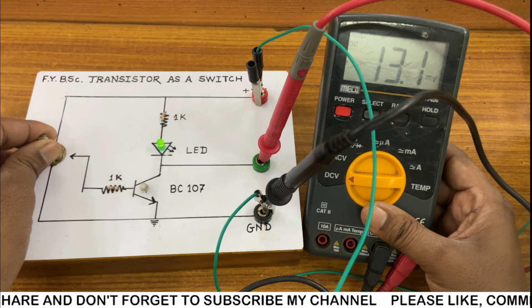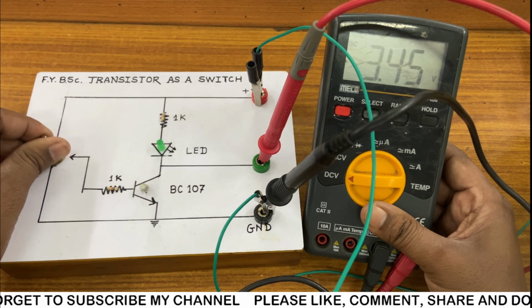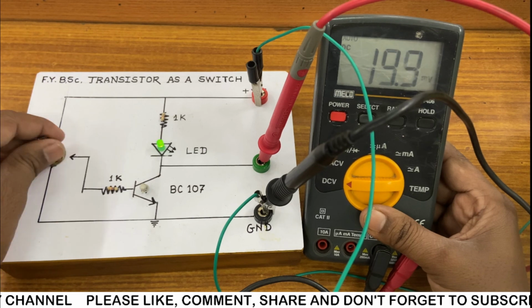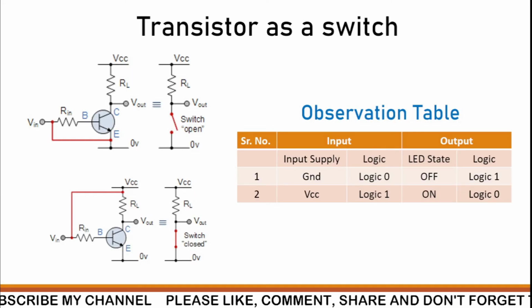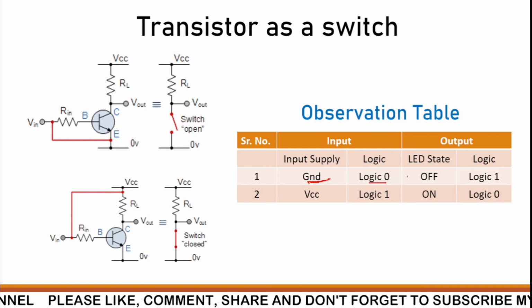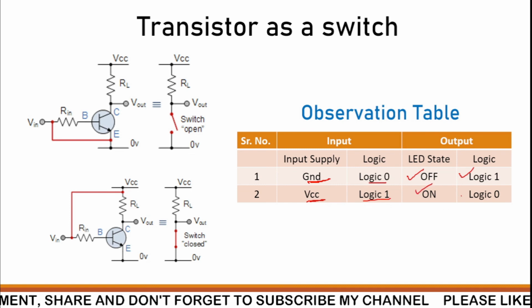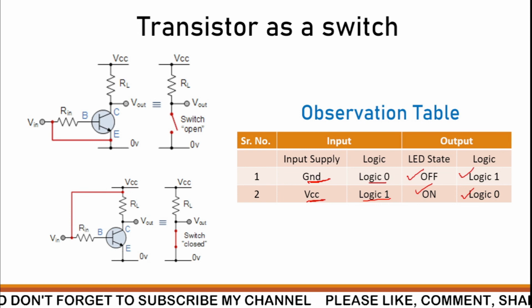I am just changing the bias of the base, or changing the voltage of the base. You can see the LED is off and we are getting 3.44 volt. If I make the biasing 0, then in this way, by having ground as logic 0, we are getting the LED off. At that time the output logic is 1. And having VCC as logic 1, the LED state is on and we are getting logic 0. So this is the way to perform the transistor as a switch experiment in the laboratory.